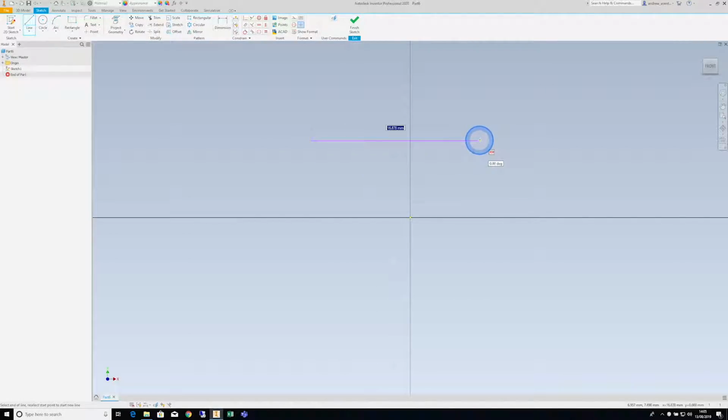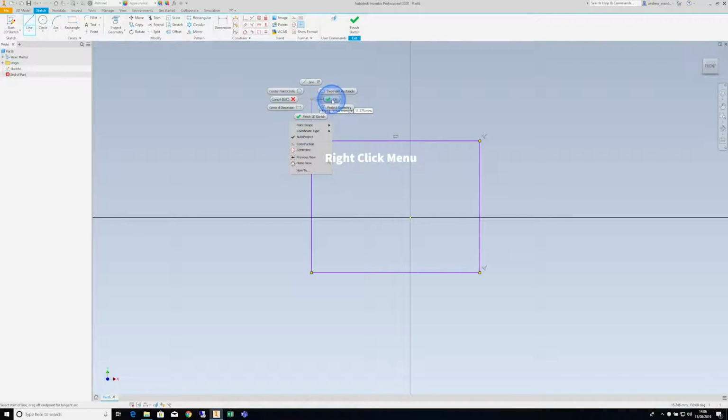It's almost like it's magnetic. You can click and that automatically applies this little constraint up here. It'll do the same in the vertical direction, and that'll automatically apply a perpendicular constraint here. You do the same thing here, and you'll find a point where it will be horizontal and in line with the end of the line above, and then you can snap to that one and you've got a perfect rectangle. You click OK to finish the rectangle.